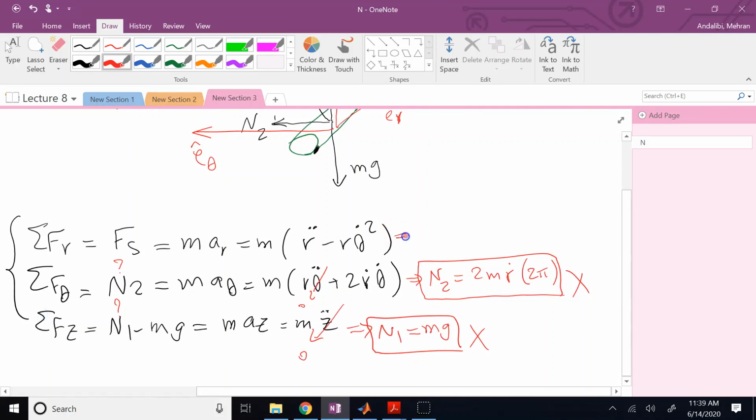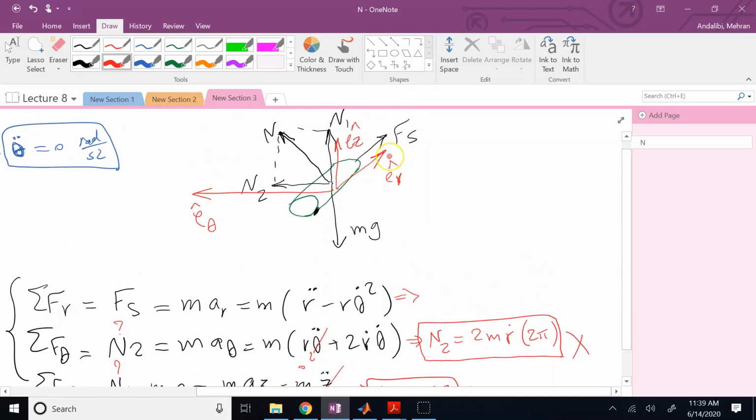In the radial direction, however, the spring force, we have to first calculate it. We know the spring force, assuming it's a linear spring here, and assuming that the displacement is not too big, which kind of it is. It's 1 meter, 2 meters, 3 meters here, but let's say k is not super big, and again, we assume that it's linear. So the magnitude of this is k times delta L, right? And delta L means what? Elongation from the unstretched position. How far have you elongated?